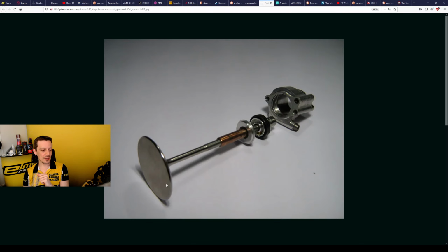That basically means the options that are left are to transfer the heat through the valve guide, and there you have a really large surface area. Of course, you don't have direct contact there like you do on the valve seat, but you have a much larger surface area, so that is the benefit of running sodium-filled valves. These will typically be Inconel sodium-filled valves. I know they have been in older turbocharged cars like Volvo 8 valve engines, so they have had sodium filled valves, and they probably are not Inconel, I would guess, at least.